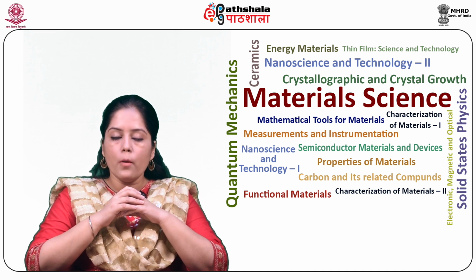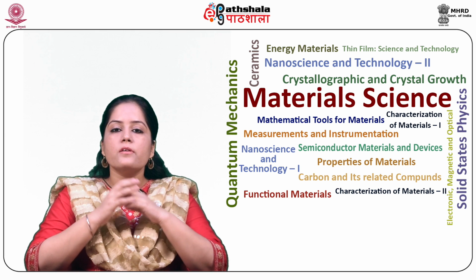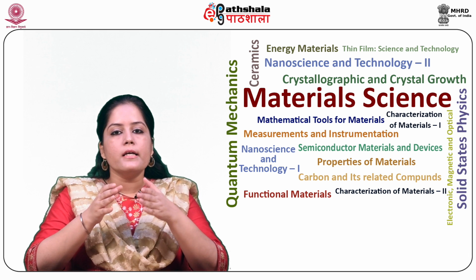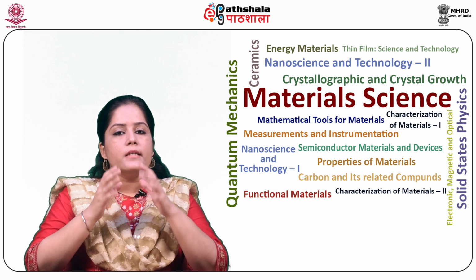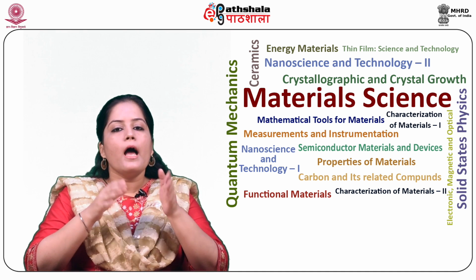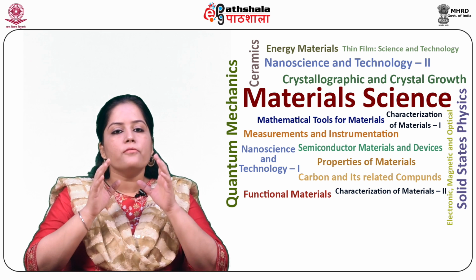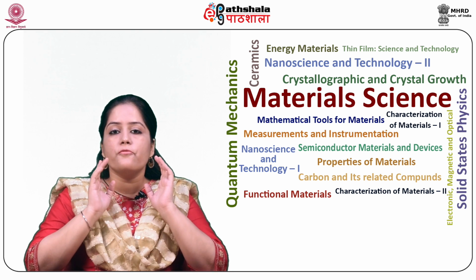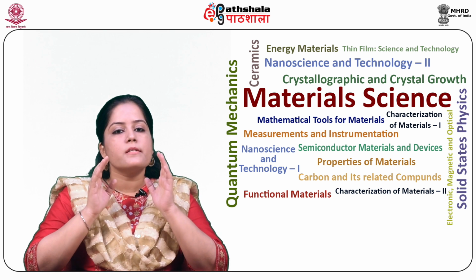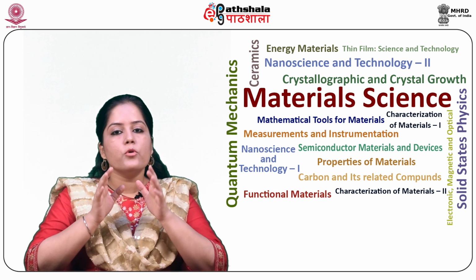Like the conventional optical lithography counterparts, extreme UV (EUV) lithography and X-ray lithography utilize photons to image the pattern on devices. But unlike their conventional optical counterparts, they utilize extremely short wavelength photons in the soft UV region for EUV lithography and hard X-ray region for X-ray lithography of the electromagnetic spectrum. Of these two lithographies, X-ray lithography was the first to be successfully demonstrated to be useful in lithographic patterning. The resolution potential of both X-ray and EUV lithographies, given their short wavelengths, was the main motivation for their development.